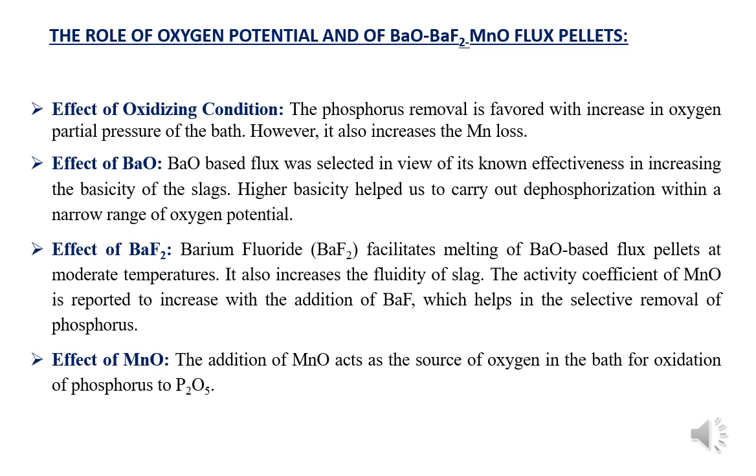Effect of barium fluoride. It facilitates melting of pellets at moderate temperature. It also increases the fluidity of the slag and activity of manganese oxide. Effect of manganese oxide. The addition of manganese oxide acts as a source of oxygen in the bath for oxidation of phosphorus.